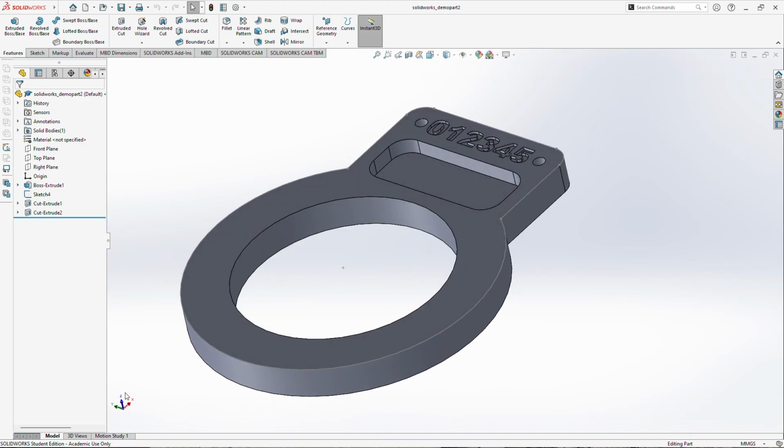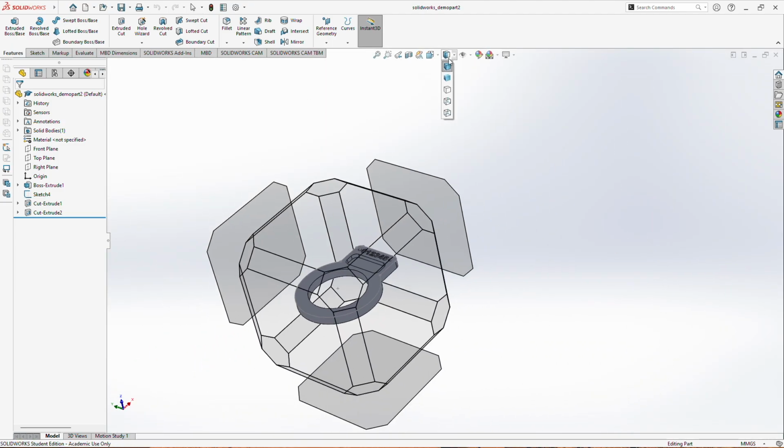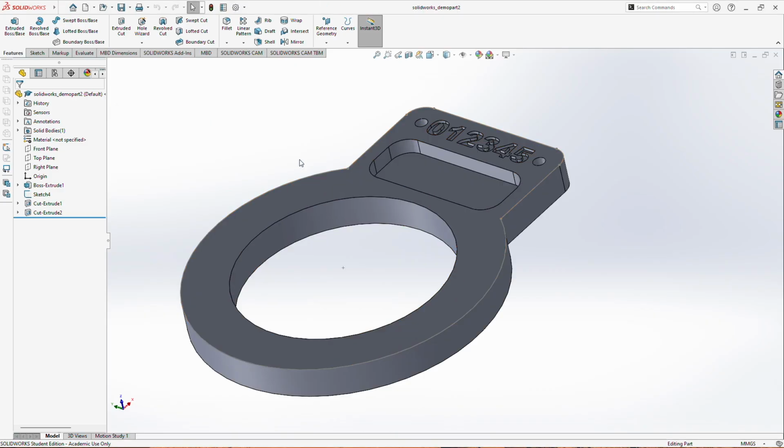So if you ever want to adjust this in your design file or even set this as your default, you can always press your view options right here, then open up more like this, and then change your up axes configuration here. And if you want, you could save that as a template so you don't have to do this every time. This is also something that can be adjusted in the CAM settings, but I find it's easier to do from the design process.